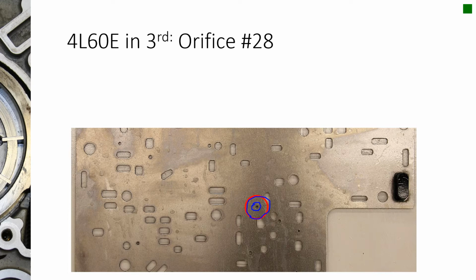the weak link in this transmission. So if you run into 3/4 clutch failures, you want to make sure that there are no leaks anywhere in this transmission on that 3/4 clutch circuit.